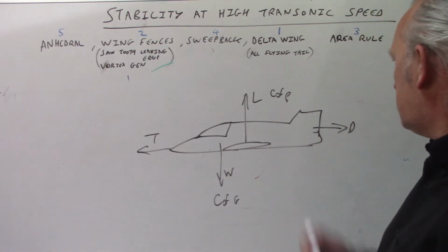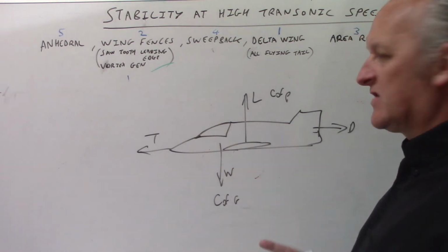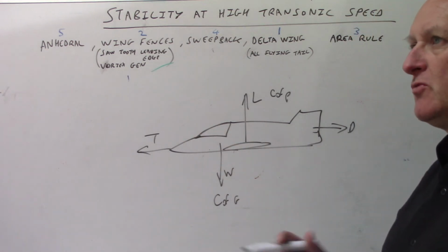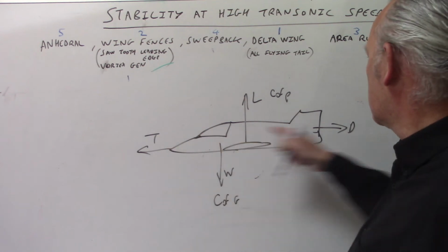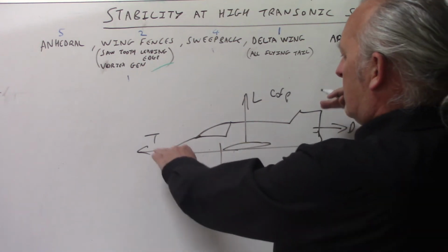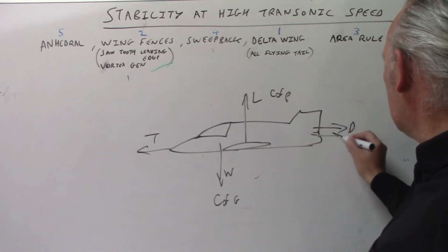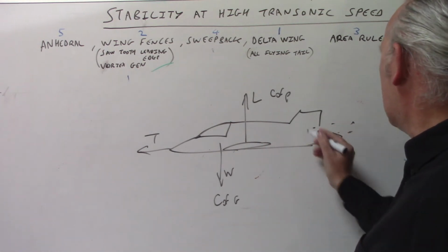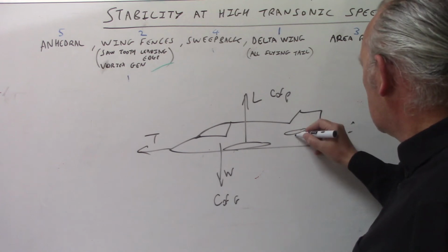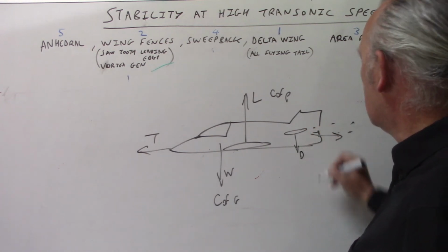If you have an aircraft that's perfectly balanced and doesn't have a lot of tail trim on it, the drag will be higher than the thrust. With a low wing, a lot of the drag is created by the wing, so the drag might actually be in line with the thrust. If that happens, you'll have a bit of downforce on the tail.